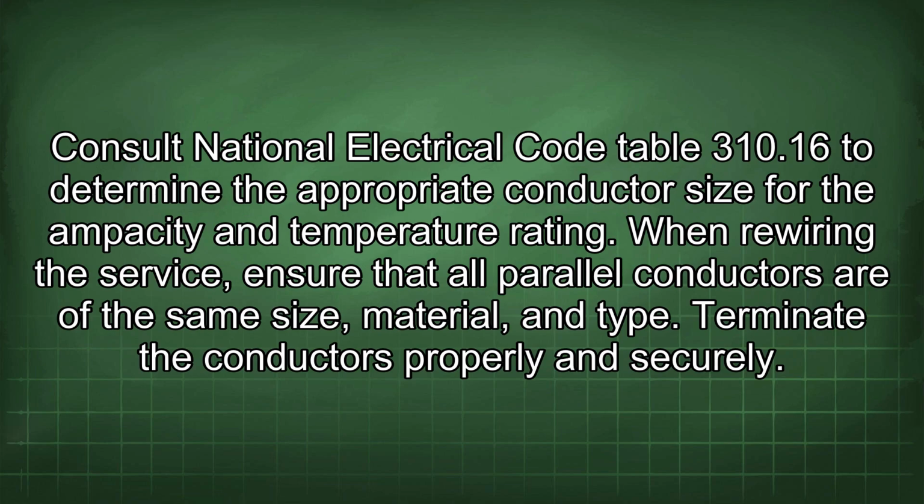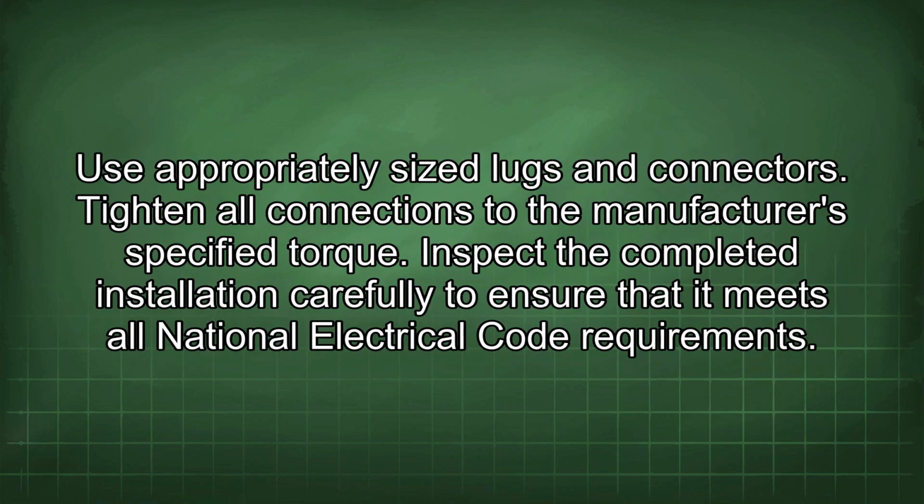Consult National Electrical Code Table 310.16 to determine the appropriate conductor size for the ampacity and temperature rating. When rewiring the service, ensure that all parallel conductors are of the same size, material, and type. Terminate the conductors properly and securely. Use appropriately sized lugs and connectors.